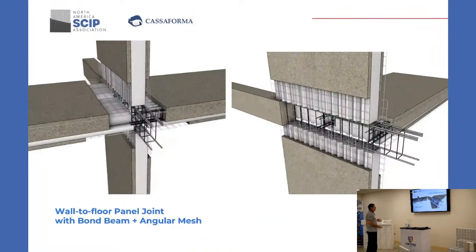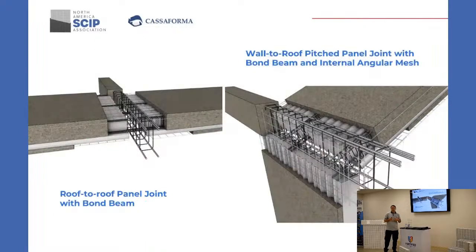Well, the same applies here. There are also a lot of details to show you how to lock in when you have panels that are not the length you need. For example, you order a panel that is maybe 19 feet and you have to go up to 30 feet. There's a way: you usually lock it like bricks.